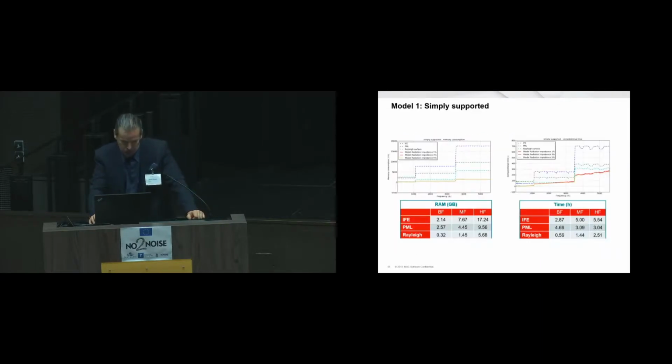And as I said, not surprisingly, at low frequency, infinite elements are better than PML. At high frequency, PML are better than infinite elements. It's the case both for memory and for time. Something to see also is that the Rayleigh integral, even if it increases the solution time because it couples the elements of the plate to each other instead of just having a localized coupling, is still much more interesting than the other approach in terms of both memory and CPU time, but it's limited to flat structures.